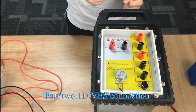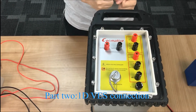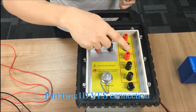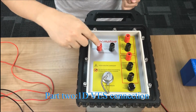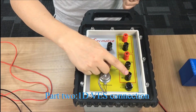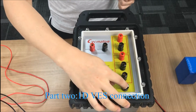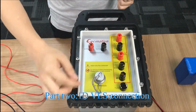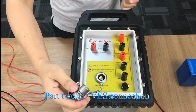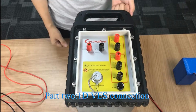Part 2. They connect the right panel of the mainframe. There is the panel with several ports. The first 2 are the power input and output. The next one is AB, the transmitter. The next one is MN, the receiver. This next port is for the Earth. The fuse port is to protect the mainframe, and the last one is the ERT tester port, which can be connected to the ERT cable.